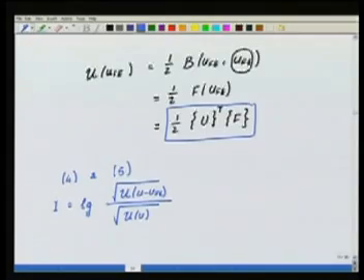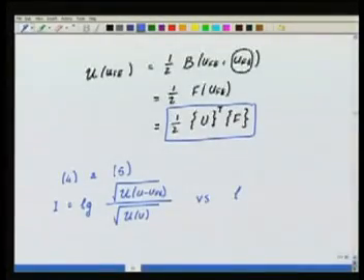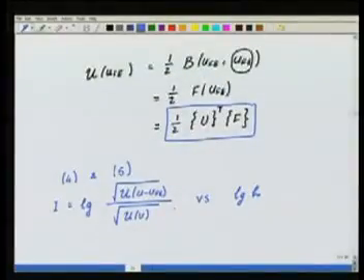So this I can essentially plot versus log of h. So if I plot this quantity, so what does it say? It is the strain energy of the error, square root of the strain energy divided by the square root of the strain energy of the displacement, log of that I take, this I call as I, then I should be able to see something very interesting when I plot.